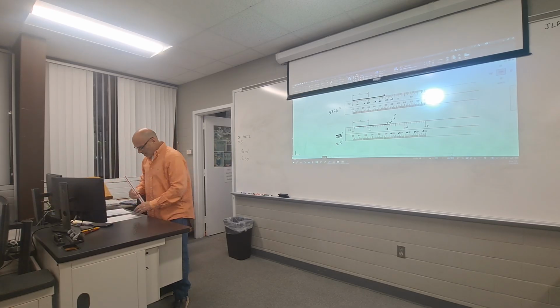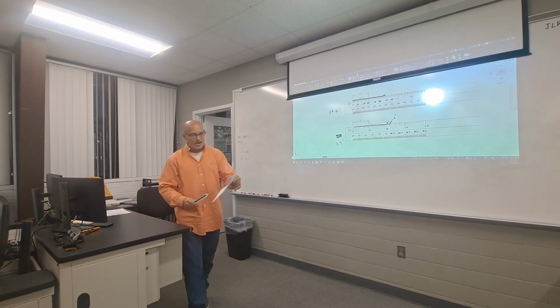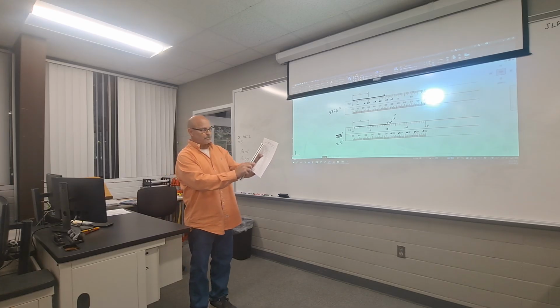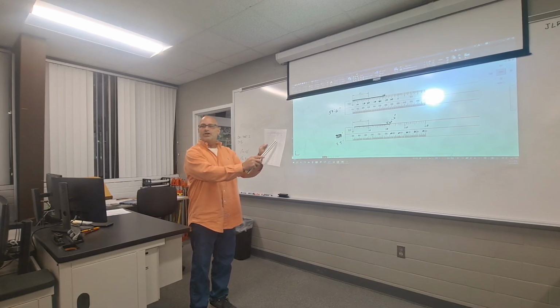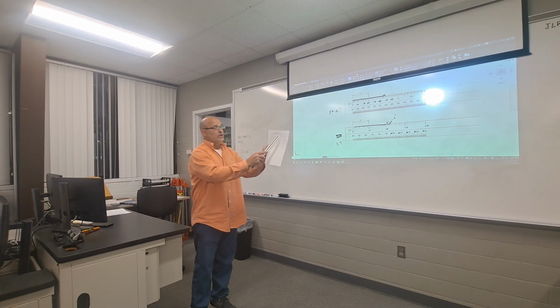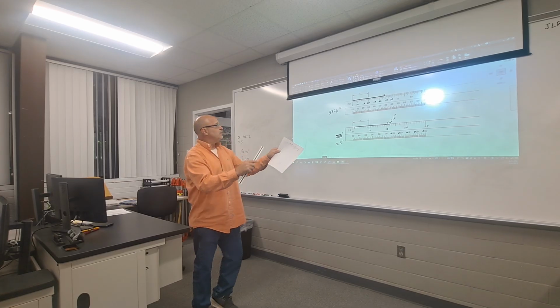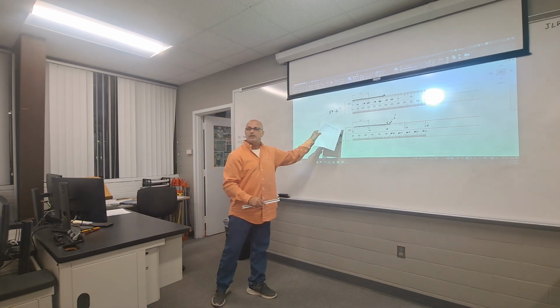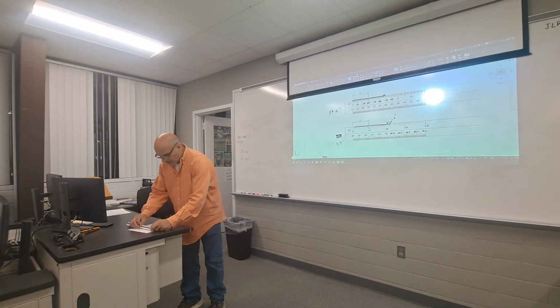Just to give y'all an idea of how it works, that first one right there is the line that you measured. It has a column that says line. You can see there are different lengths. The next column right here, 1 inch equals, is like your scale. The first one is 1 inch equals 10 feet, so I'll go with that one. So I'm going to turn my scale until I see the side that has the 10 on it, and I'm going to stick my scale on it,